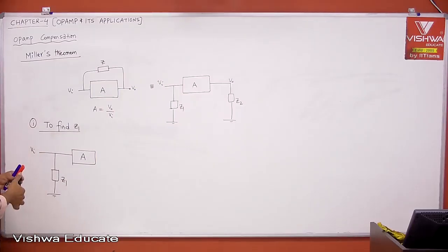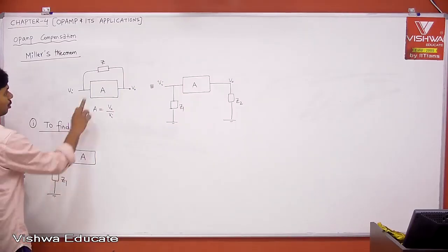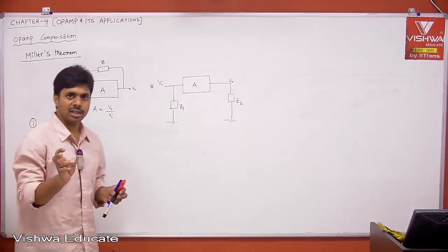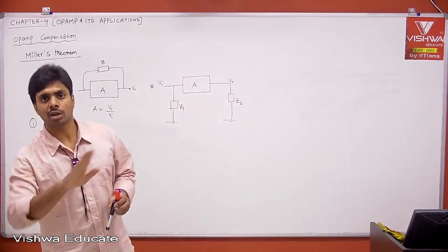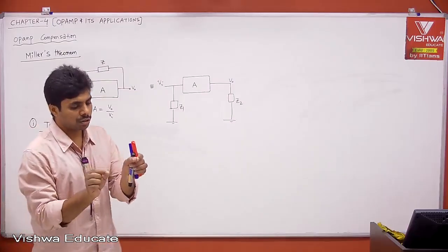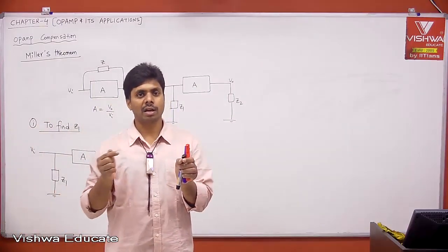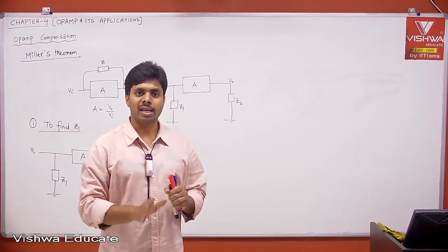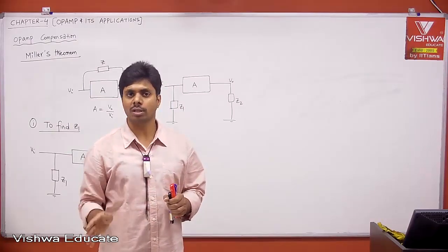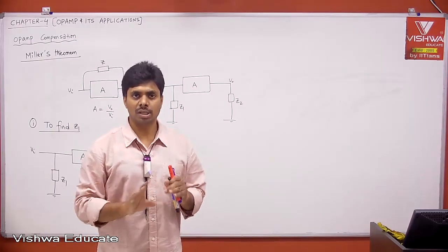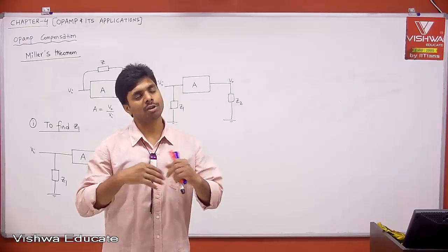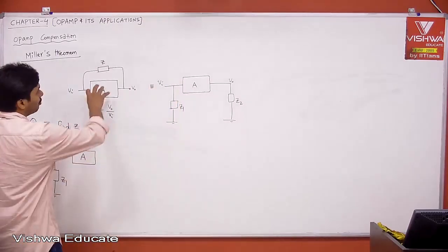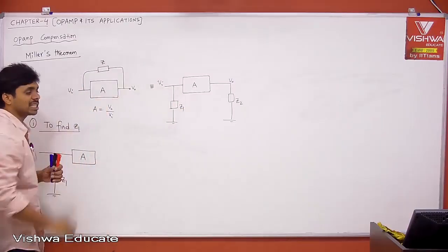Let us say both are equal. When can you say both are equal? If KCL and KVL equations are not disturbed, meaning the voltage drop across the element, or the current flowing through a node, is not disturbed. Until you disturb KCL and KVL, we can modify the circuit in any way. Therefore, this is a kind of modification, but we should not disturb KCL and KVL.